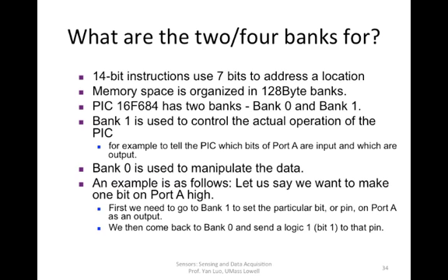On the other hand, the registers in bank 0 are used to manipulate data. Use the same pin as an example. If we use pin 2 as an input pin, a digital input, we can use a register from bank 1 to configure the pin as an input. But if we want to get the actual value of that pin, we need to access the special function register in bank 0. That's what we mean by manipulate the data.